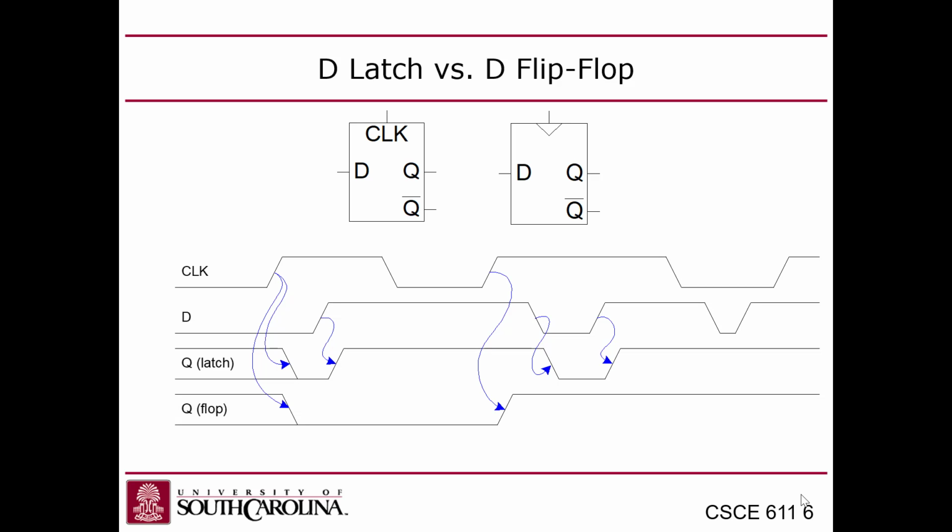But latches and flip-flops have a clock input, which is assumed to be some regular periodic square wave. A latch will take whatever's coming in the input, which is called D, and the input is, by convention, called D in both a latch and a flip-flop. I think D stands for data. I don't know what Q stands for, though. Never figured that out. But D is the input, Q is the output. These are also shown with a complemented form of Q.